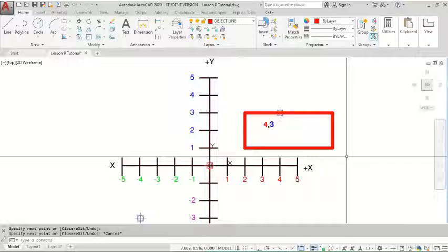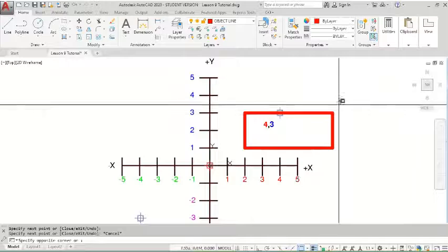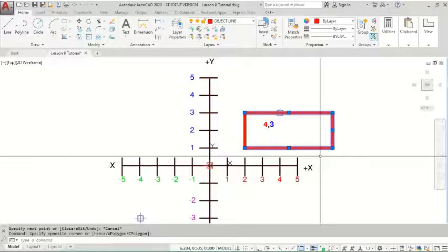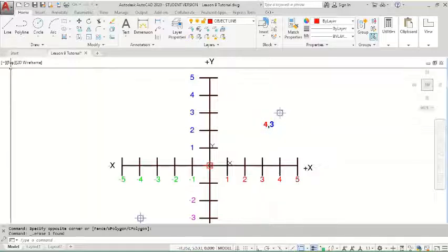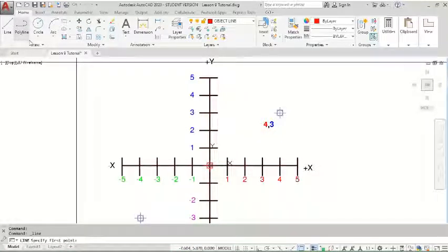And then page 9-5, it just gets you to go through and practice using both of those. So your absolute coordinates and your relative coordinates. So make sure you try that little example that's shown in scenario number 3. And remember to turn your F12 button off. So I'm going to run through that little exercise in scenario 3 quickly, just to show you. So I'm going to start. It says my first point is 2, 4.